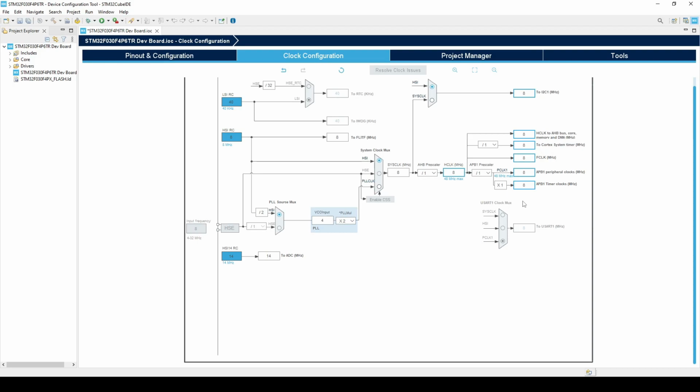So you may be wondering, why would I use an external crystal when there is one internally on the microcontroller? As we just said, it saves me routing, saves me a bit of money on the crystals. I don't need to faff around with all this and see if my crystals tune correctly and whatnot. And the thing is, it really is dependent. Like a lot of things, it's really situational, though I must say that you need to consider the accuracy, because internally it is not that accurate, even though it just says factory trimmed. It really depends on the accuracy and timing of your application and your project. So this is why it might be best for you to opt for an external crystal instead.